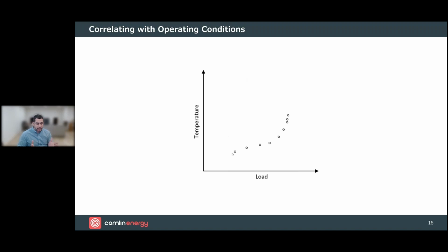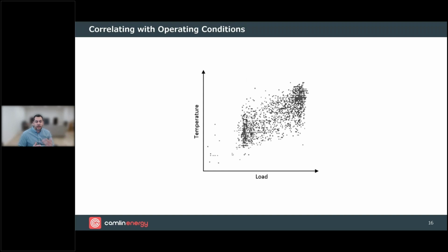But if it can be done in an online sensor that does this automatically through normal machine cycling, you would collect the same information from continuous online monitoring, okay? So saying we collect all these data points and we have the severity of the partial discharges indicated here for all these data points, we're now able to extract information about where the partial discharges are most damaging. So colored in red, we can see in this case high electric discharges in this region of the map. Okay, so at low loading, we see higher partial discharges in this example.